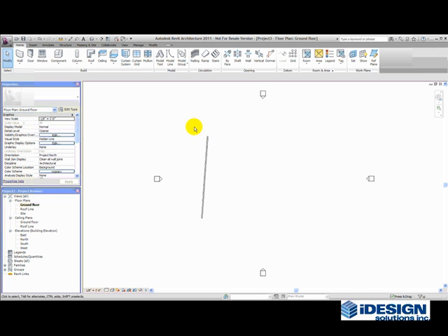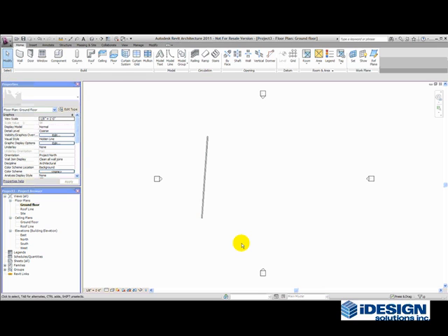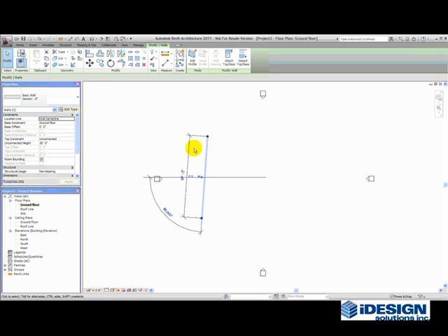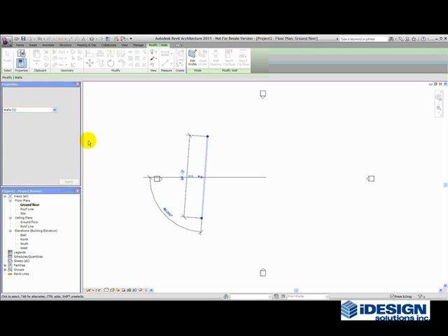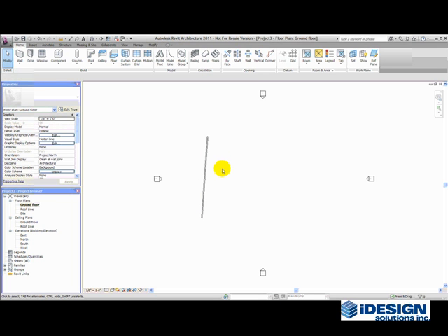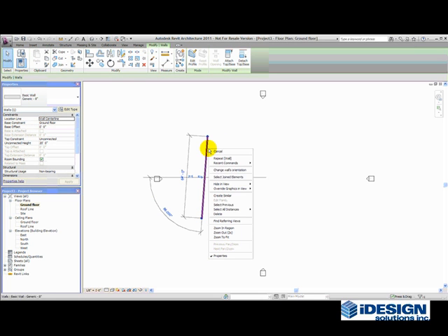While Modify is selected, you can highlight a specific wall by window selection, left to right, double escape to clear it, or crossing selection, right to left. When you select it, the properties dialog box gives you all the options to make some changes. And of course, if you want to delete it, I typically highlight it and press the delete key, or right click and select delete.